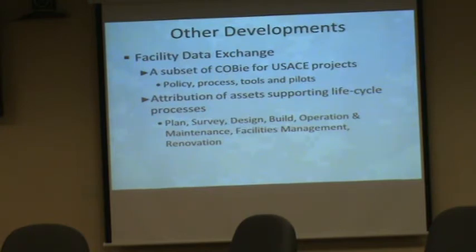Adam, you're mechanical here, I'm barely a mechanical, they're using the model in there, and let's say SAP tells the work order guy of the day that I did a vibrational analysis on this VAV box and it needs to be replaced. Then the BIM model comes into play and it lights up, hey, this is where that VAV box is, and here's the information about it. That's the kind of stuff they're using the model for. And COBie is just a way to structure the data.